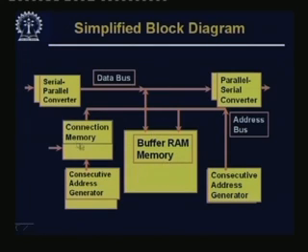There is a connection memory, which is that mapping table that we have talked about. So, when you are setting up a connection, you will make entries into the connection memory. We will just have a look. The connection memory is what we have already seen, and then there is a consecutive address generator here, and then from the buffer memory once again it goes to the output side, and then there is a parallel to serial converter for feeding into the individual line. So, this is the data bus and this is the address bus.